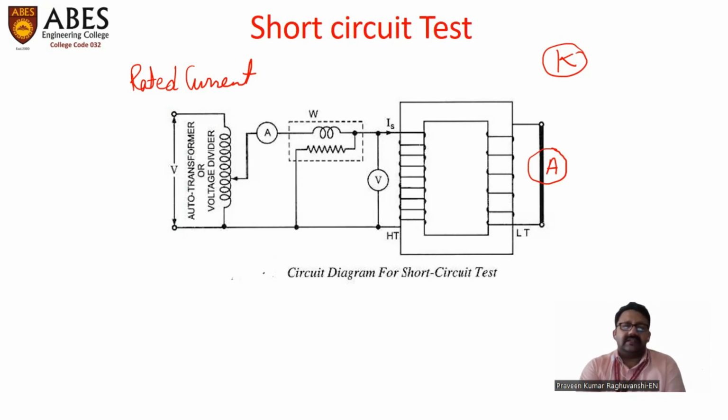As the voltage is slightly increased in very small steps, with the application of a very small voltage, a weak magnetic flux is developed on the primary side and the transformer action takes place. Due to this transformer action, flux links with the secondary winding, and a considerable amount of current starts flowing.